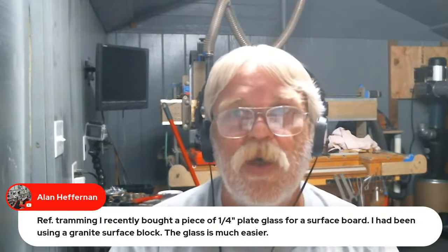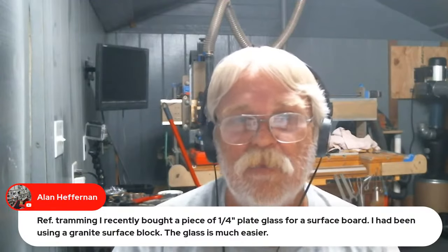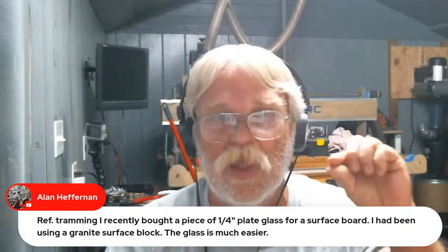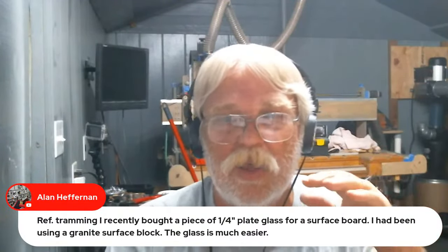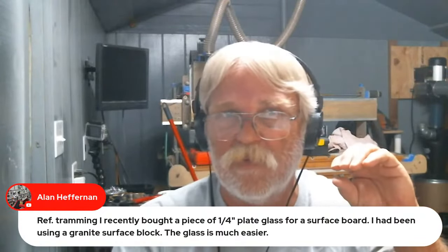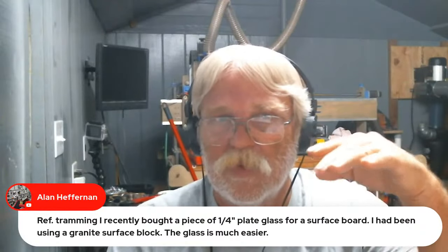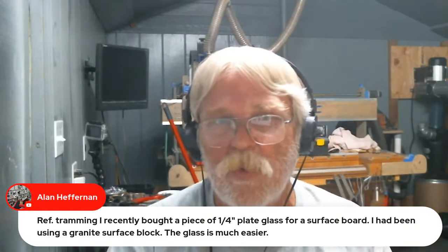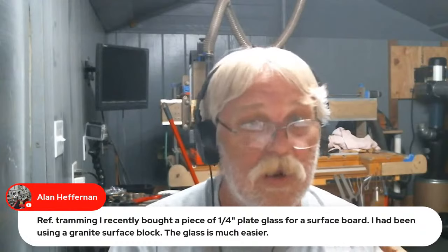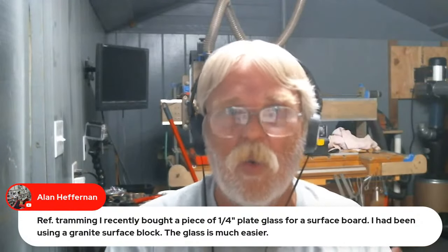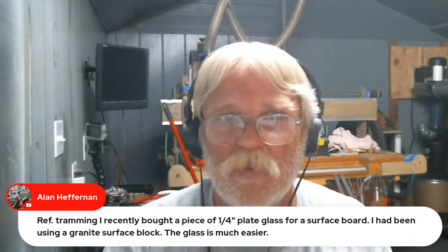The first tramming video I did on my channel, I made the mistake of using 1/8-inch thick glass. What I didn't realize was it was just big enough that the center sagged a little bit, and that was just enough to throw me off slightly. And again, I got into that squirrel cage where I was chasing zeros.